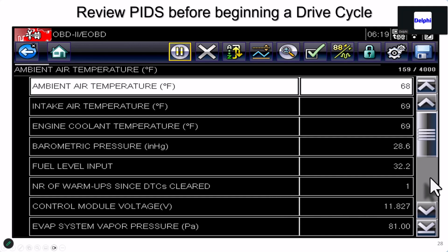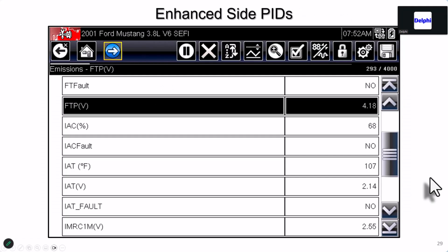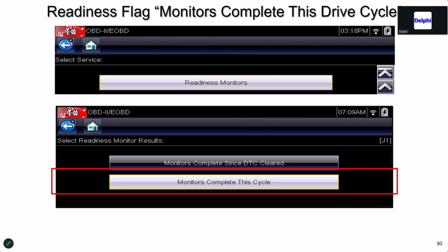And this driver seat diagnostics shouldn't take you that long. Occasionally you've got to go over to the OEM side if it's a pre-CAN car to find some data that you're not getting on the CAN list. So don't exclude the enhanced side, pre-CAN and post-CAN, for some of the PIDs that you might want to look at. But for global OBDII CAN, you should be able to find quite a bit there.